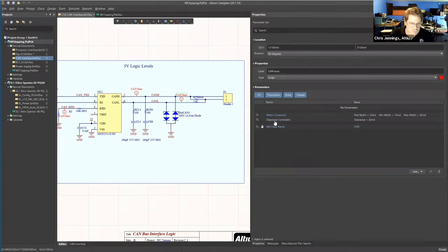And they went through all this process, and then they wanted to generate schematics from that. And I had to tell them the sad news that that's not how it works. Everything should start from the schematic. And needless to say, he was a little upset and had to do everything all over again because nothing matched anything anywhere. So don't make that mistake. Obviously, start with the schematics, drive everything into the PCB.